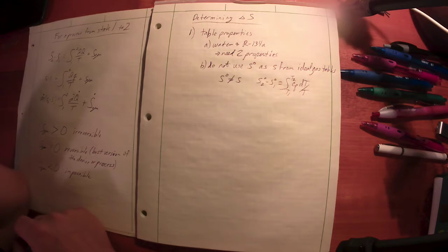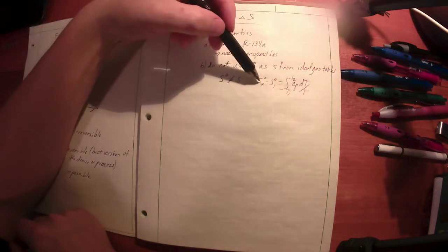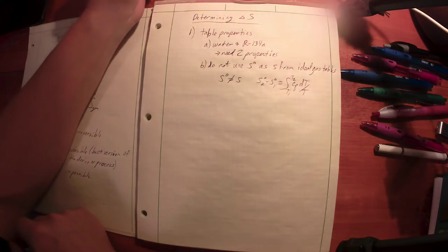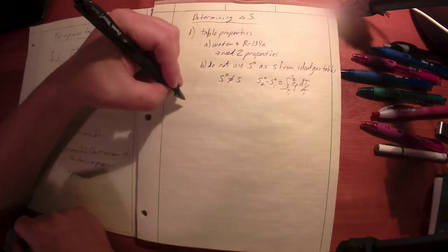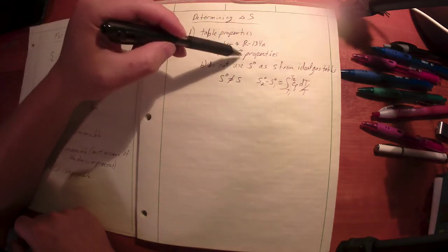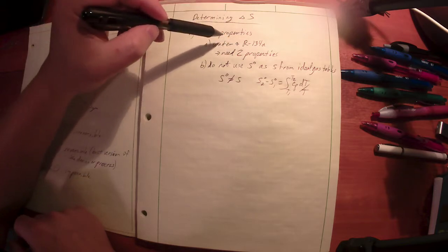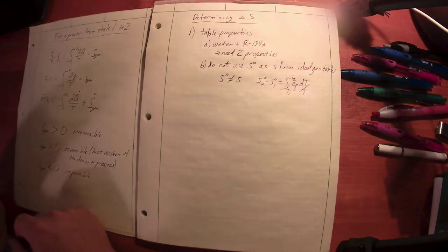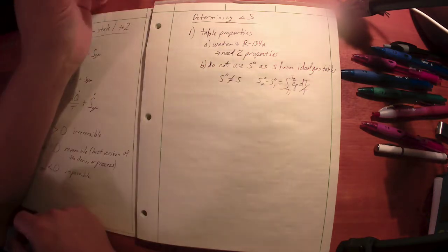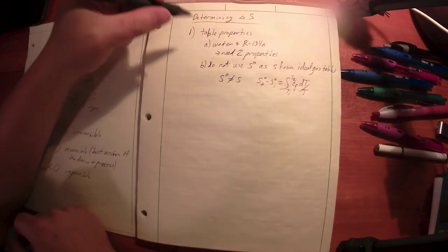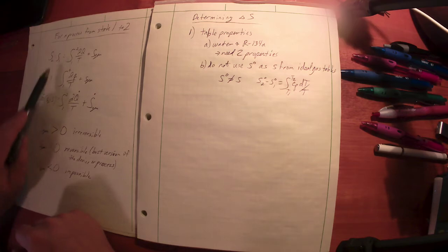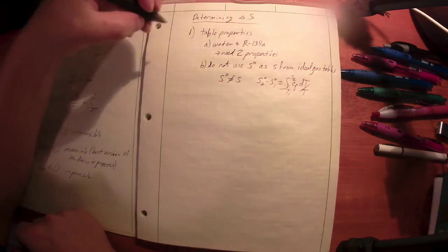But these are not S's. This only accounts for the temperature portion of the entropy change for ideal gases. There's also the entropy change based on other properties we'll see later in the Gibbs equation. So for water and R134A, these are actual S values. You can use those out of the property tables. The S values in the ideal gas tables are not actually S values. They're part of the entropy change, but not the whole picture. So don't use those directly as the S values. For water and R134A, you can plug those in right here. Use those as S values. That's just fine.